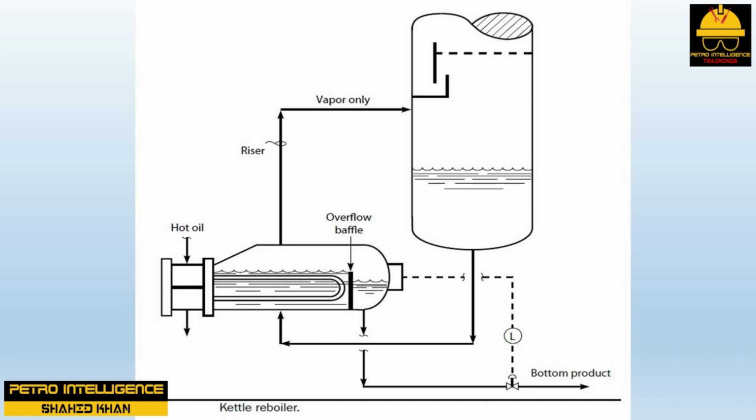The liquid level in the bottom of the tower is the sum of the following factors: the nozzle exit loss of the liquid leaving the bottom of the tower, the liquid feedline pressure drop, the shell side exchanger pressure drop, which includes the effect of the baffle height, and the vapor line riser pressure drop, including the vapor outlet nozzle loss. Note that it is the elevation, or the static head pressure, in the tower that drives the kettle reboiler. That is why we call it a gravity-fed reboiler. Also, the pressure in the kettle will always be higher than the pressure in the tower.